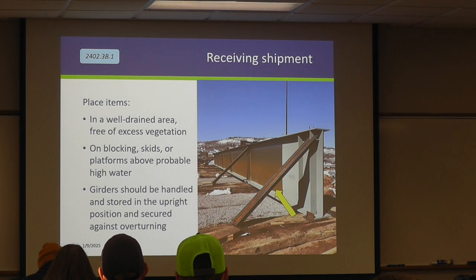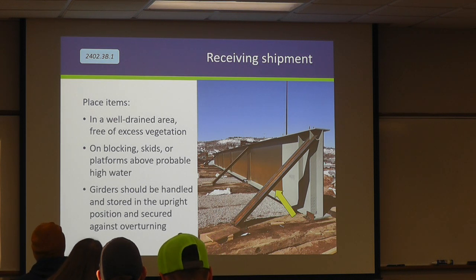So you've gone through all these checks, everything looks good. Typically, the contractors like to have the trucks come and then place it right onto the structure itself. But if you do have to stockpile it, store it on site, just make sure it's in a well-drained area, you don't have vegetation all over. We always want them up on skids because you never really know if they're going to ultimately sit in a pile of water. I was on a job in Grand Forks. Red River was starting to flood, and it took the contractor 2 days to move all of their rebar out of where it was going to flood. Right? So it's important to kind of think ahead a little bit, especially when you can understand the schedule.